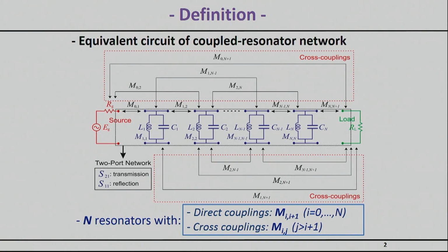So as we have seen before, a typical bandpass filter, or any other filter actually, will consist of a series of resonators shown with this blue color here. Those resonators will be coupled to each other through the inverters, and the inverters are actually shown here with these coupling coefficients M, so they're not explicitly shown with the little boxes that you saw before.